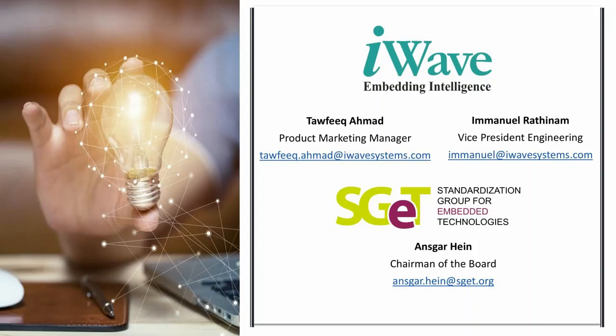And going on to another question from Alberto. The slide says 2 into LVDS. Yes, you are correct and we are wrong. In terms of specification, it's a single LVDS, but it's a dual channel LVDS. The specification defines one LVDS, but dual channel. You can have 4 pairs plus 1 clock pair in one group, so totally we have 8 data pairs and 2 clock pairs. That means obviously it's 2 LVDS. You can have full HD panels. But the specification says single LVDS, although a dual channel can be connected.